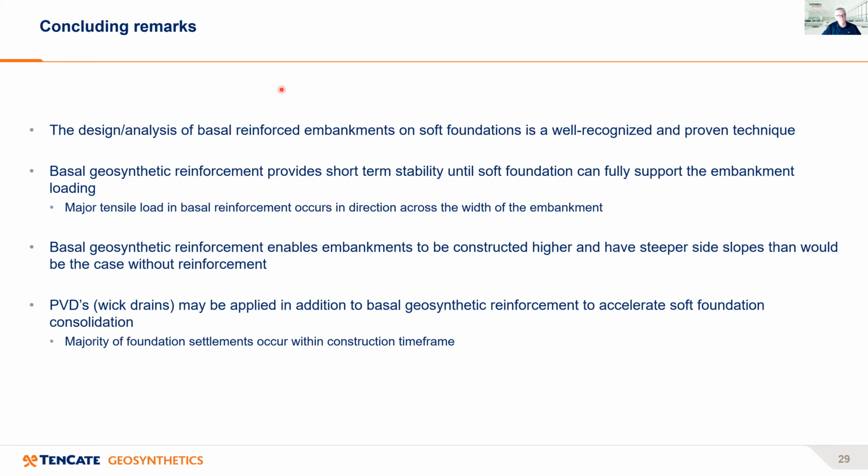And the way this is designed and planned is to have the majority of the foundation settlements to occur within the construction timeframe, so that once the construction timeframe is completed, then the contractor doesn't have to come back later and carry out quite costly maintenance, which may occur during subsequent years.